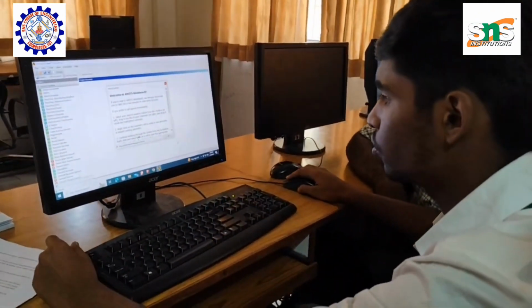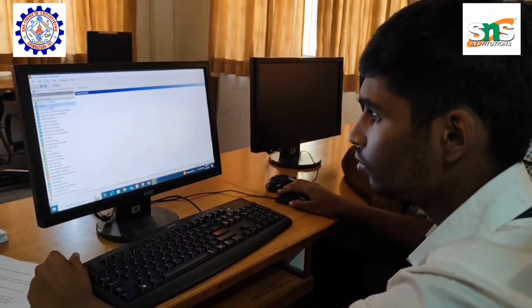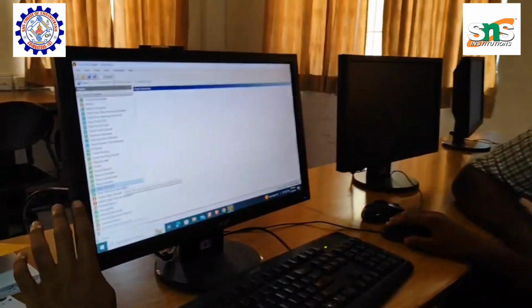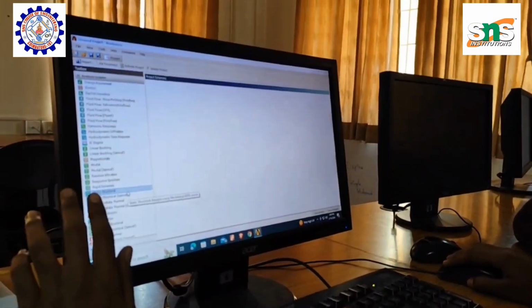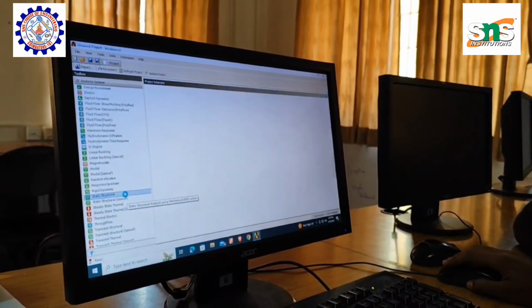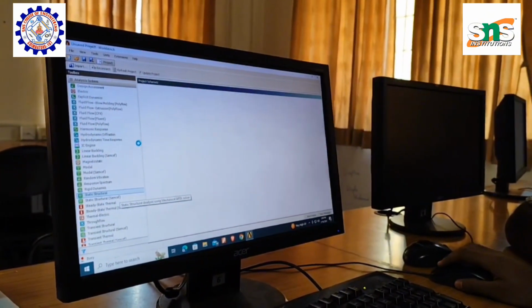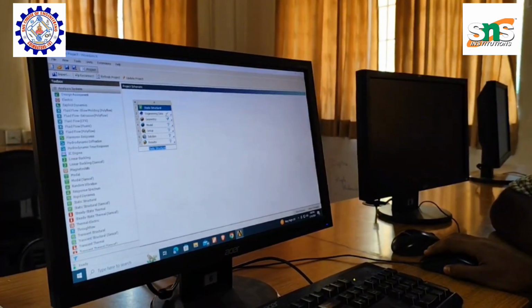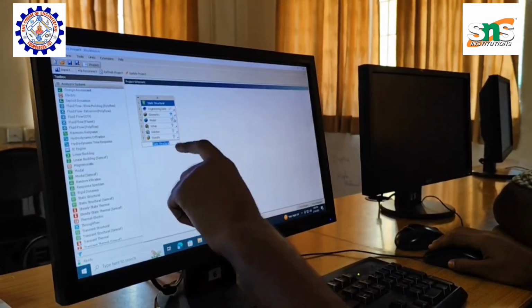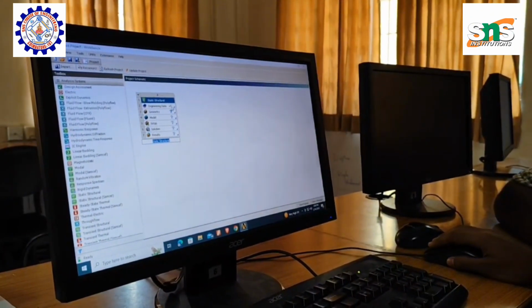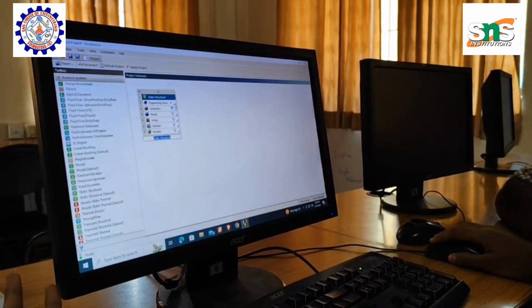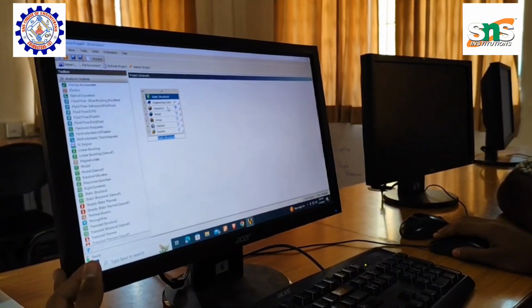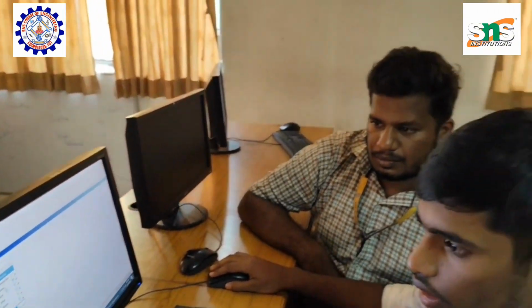Now it is opening. Now we are going to see the static structural, so I'm going to select this one. Then for everything, it should have a green color tick mark. Engineering data, we can keep as the default one. And now we are going to select the geometry.